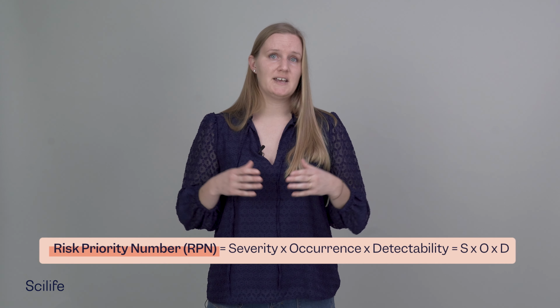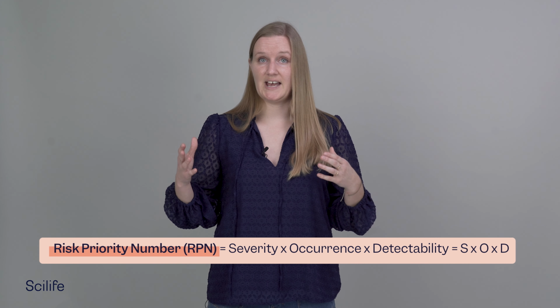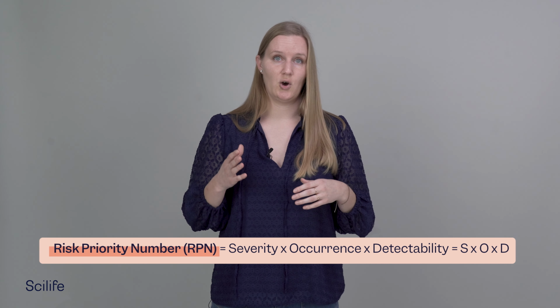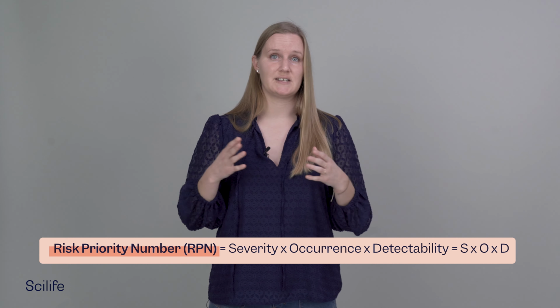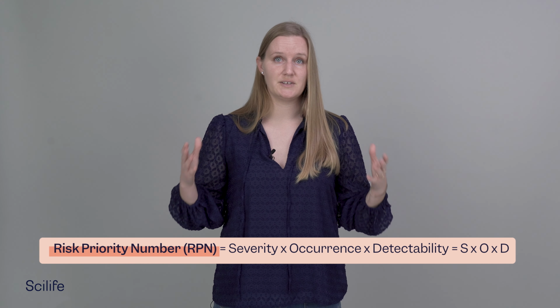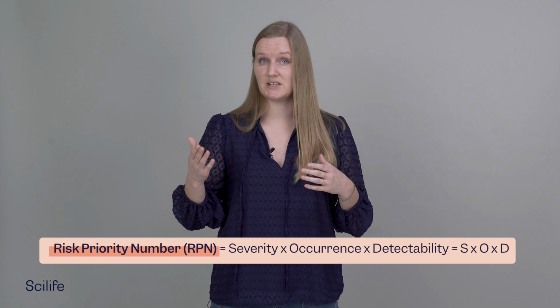The risk of failure can be determined by the calculation of risk priority number, RPN. The RPN is determined by the multiplication of three factors. Severity, S, is the consequence if a failure occurs. Occurrence, O, is the probability of frequency that a failure occurs. Detectability, D, is the probability that a failure is detected before the impact of the effect is realized.